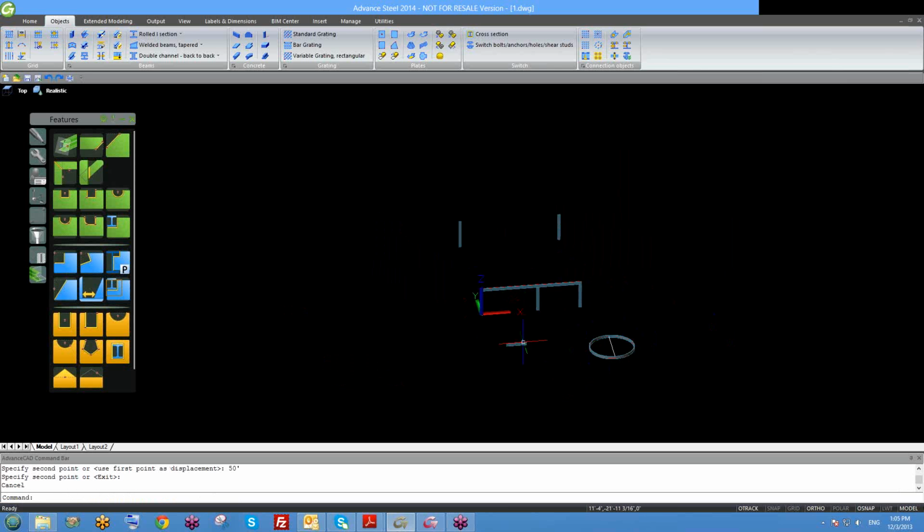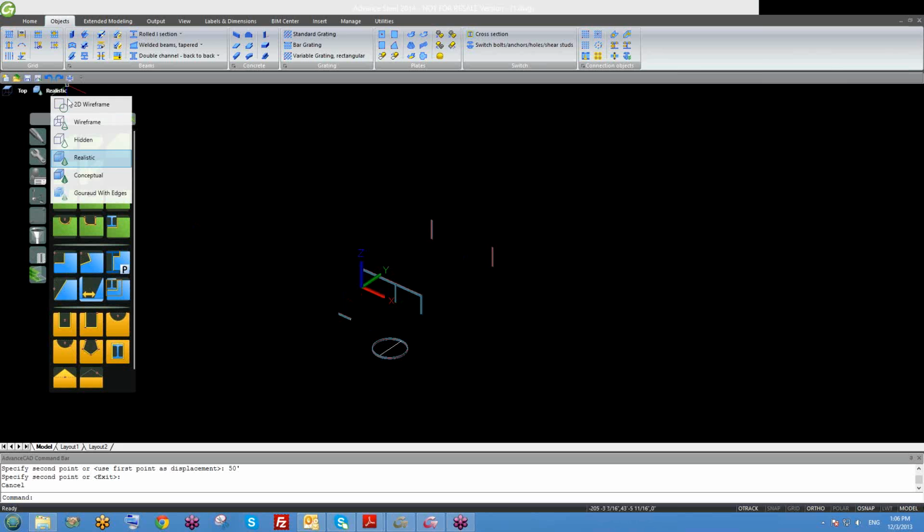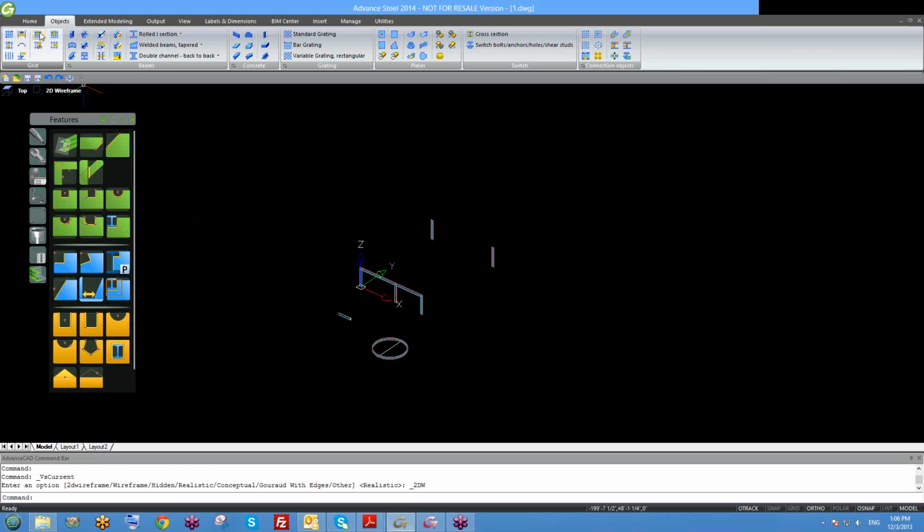If I have my model imported from another software, like Tekla or some engineering software, and I don't have my grids, but I have my objects, my beams, my columns, and I want to create axes between these imported objects, I can use this building grid.